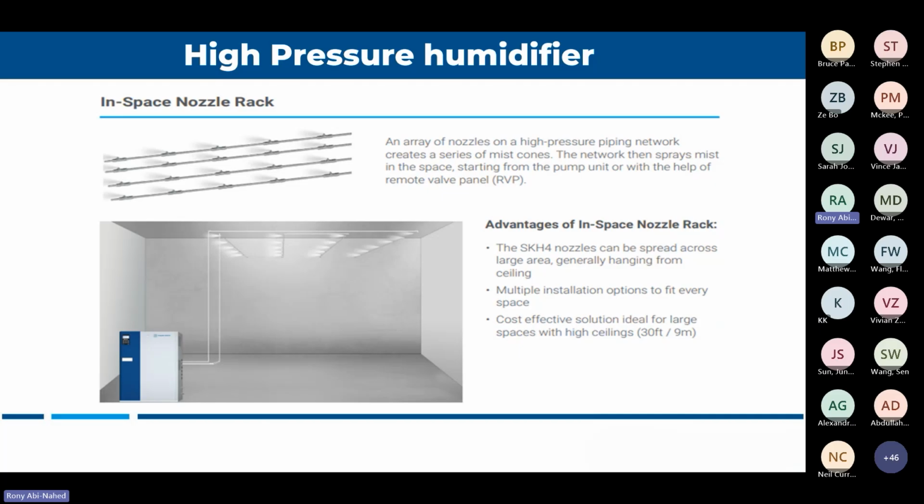So where we use this application, mostly we use it in factory applications. Let's say a printing industry. Printing industries usually have high ceilings, tons of printers generating heat even during winter, and you need humidification for the ink, you need humidification for the papers. So you shoot this sprayed water inside the space directly, you are cooling down, humidifying, and it's free cooling because these units do not consume a lot of energy.